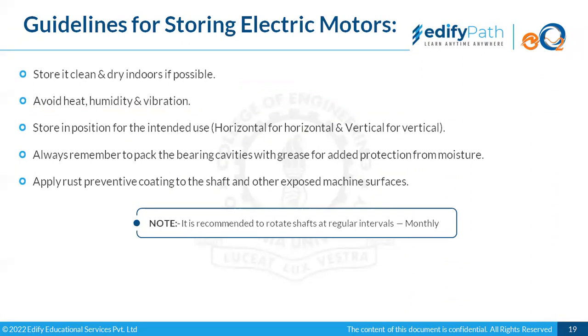This should be done in a timely manner so that we can extend the life of the motor. It is recommended to rotate the shaft at regular intervals, monthly. So it should always be recommended that we should not leave the motor for a very long time. We should not leave it unattended.